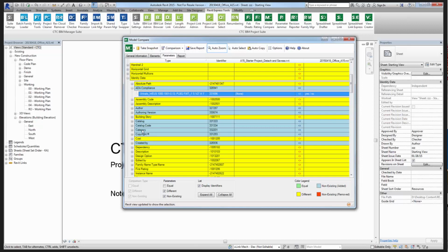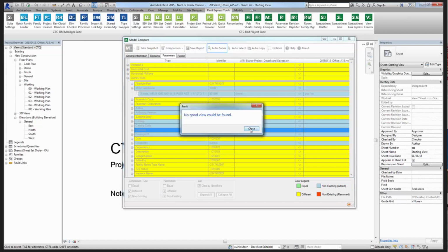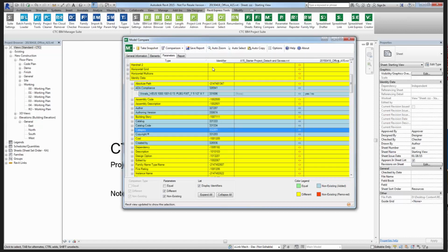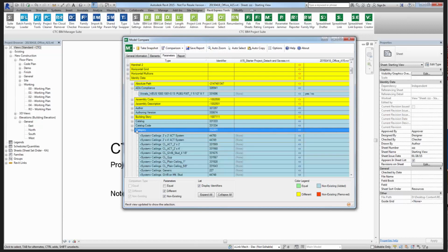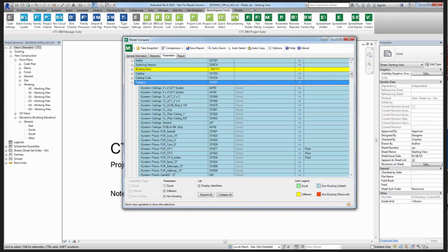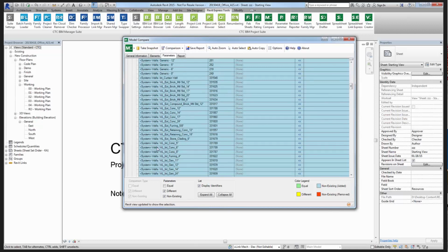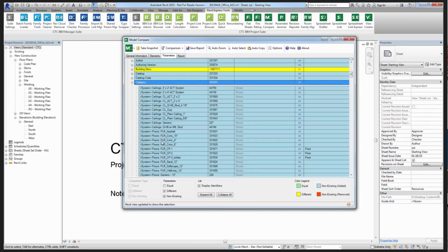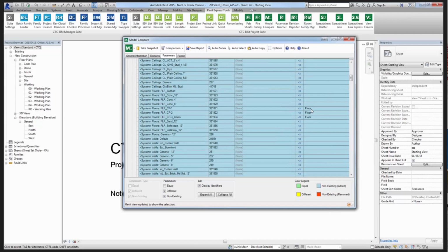If I'm looking inside of here, there's a category parameter that shows up. And as I'm clicking on this, by the way, I have auto zoom turned on. I'm going to turn that off so it stops trying to zoom to different things in my project. Since I'm looking at type data and parameter data, it can't actually find a view to look at because it's data. But there's a category parameter here, and for whatever reason, when somebody built these components on some of these floors, this FLR, CP1, CP2, and CP3, there is a parameter called category that applies to apparently ceilings, floors, walls, and a couple of other objects as well. Apparently it's quite a few objects, and in some cases it has a data value on it.